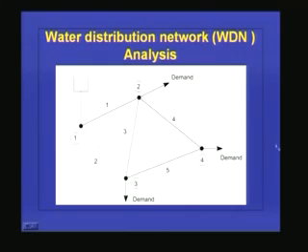at all the nodes. Please note, the piezometric head at node 1 is known because node 1 is connected to a distribution reservoir. If I know the water level in the distribution reservoir, then I would know the piezometric head. So the piezometric head at 1 is known, but 2, 3 and 4 are what I am trying to find out.